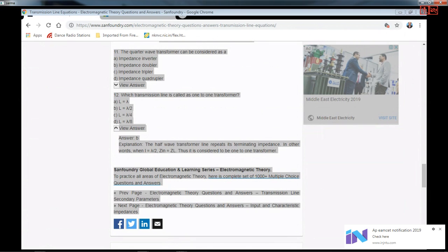Please remember, S is a dimensionless quantity. So with one number, you can indicate whether the line is behaving well, or in a not so well or very bad situation. If the line impedance is very much away from the load impedance value, then the VSWR value is going to be very high, like 2.5, 3.6, or 10, 8, or some numbers like that, indicating that the line is thoroughly mismatched.